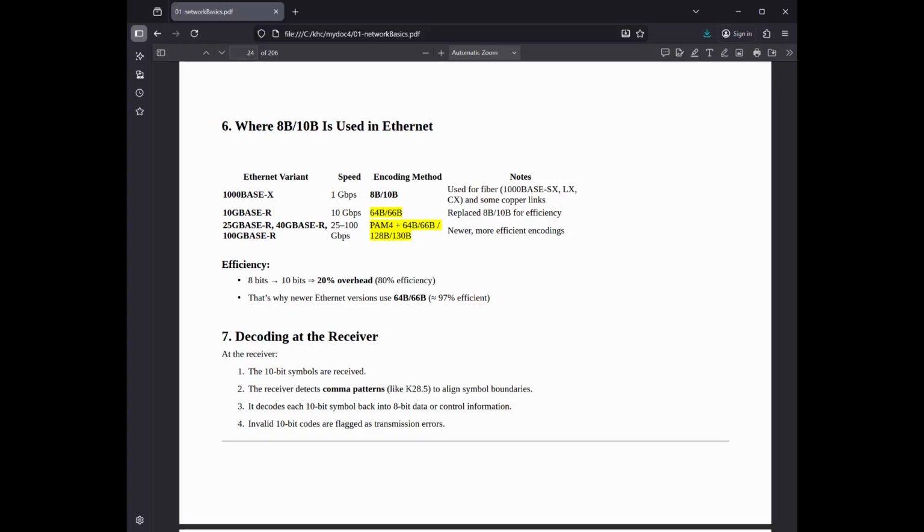10 gigabit Ethernet, for example 10GBASE-SR, 10GBASE-LR, 10GBASE-T, 40 gigabit Ethernet, 100 gigabit Ethernet and higher speeds. 128B/130B encoding. This scheme further reduces overhead to about 1.54% and is primarily used in high-speed interconnect protocols outside of Ethernet, such as PCI Express 3.0 and later generations, as well as USB 3.1.